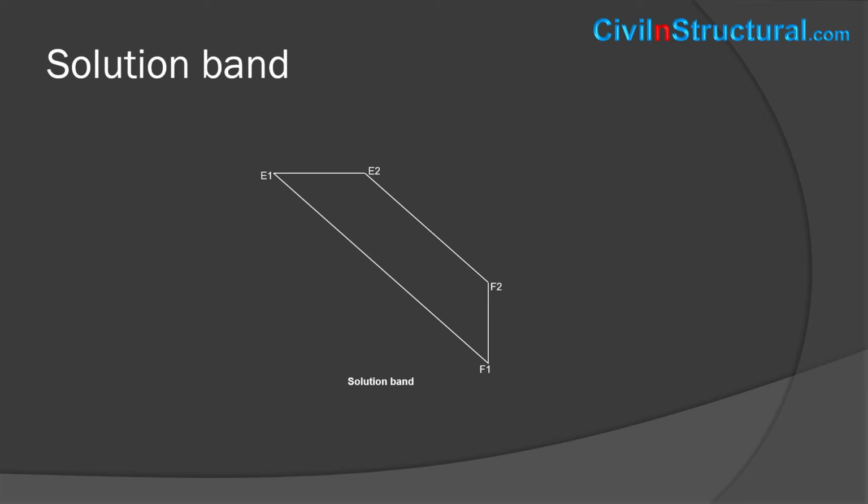While doing this, just store all the information regarding volume and location of CG for each and every case, and find the location where the total error in pressure volume plus CG along X plus CG along Y is minimum. This is the procedure to be followed while doing the actual programming.